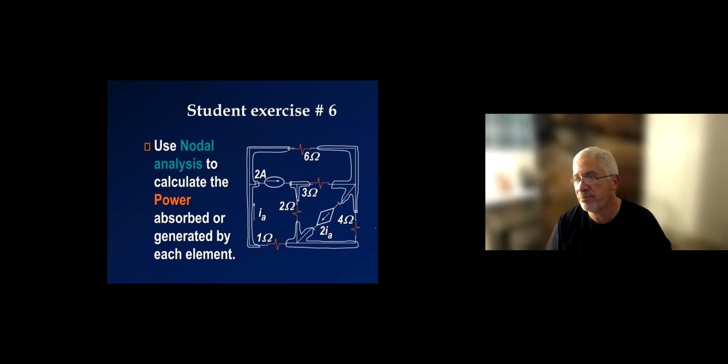That means 3 unknowns. Of course, the next step is to select the reference node, label the other nodes, and then put current on the resistors. But I wanted to show you that step, kind of doodling it, so that you can make sure that it is absolutely essential that you get it accurately. Okay, so let's see where we go.